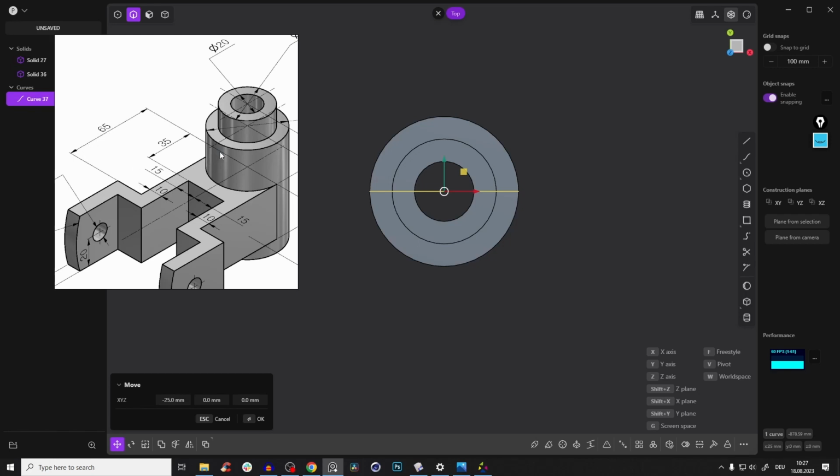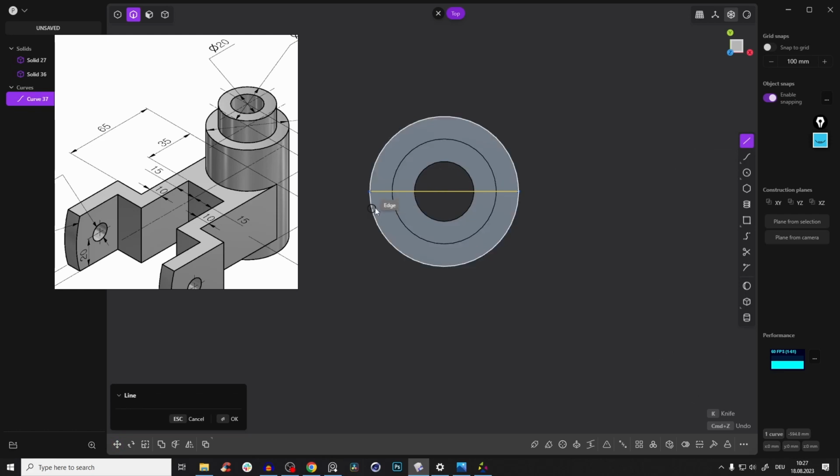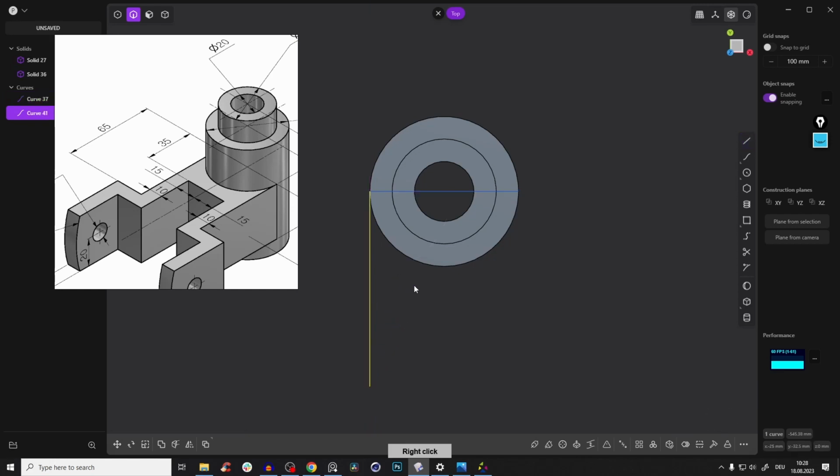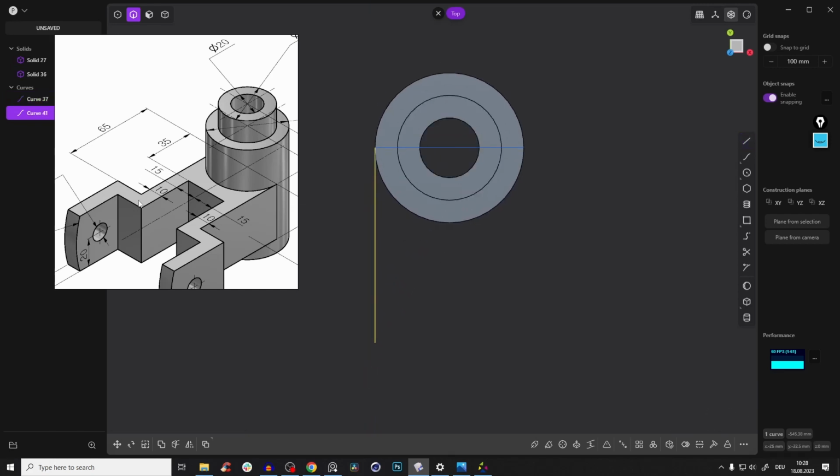So we just know that this line will start at this point and just go straight 90 degrees in 65 millimeters. So create a line, snap here, beginning curve, intersection, and just drag that out. Press again tab, type in 65. Be sure that you snap here to the normal Y direction, right click, and perfect. So we have here our first edge.